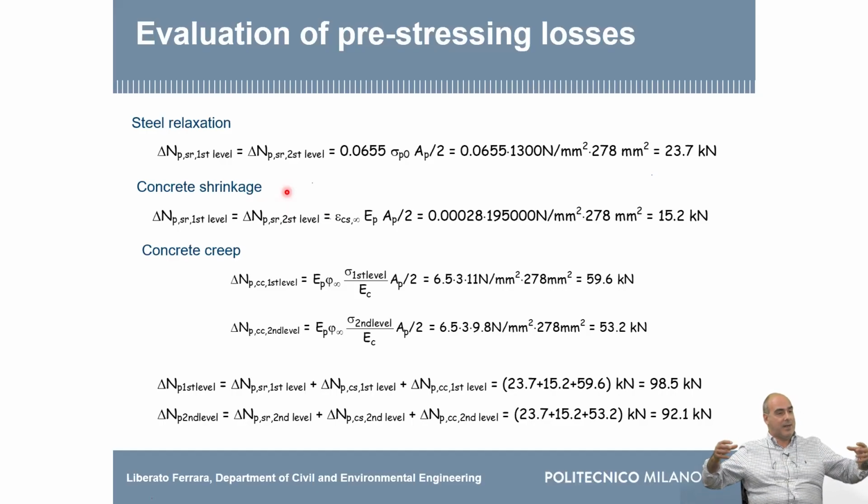When the pre-stressing steel is embedded in concrete, it's not experiencing a constant stress. It's rather experiencing a constant deformation, because it's the concrete which freezes it in that situation. When you have a constant deformation, over time the stress which is needed to keep this deformation constant gradually releases. So this is the relaxation. In steel, it's due to the fact that steel is not a molecule. You cannot write the chemical formula or the chemical graph of steel.